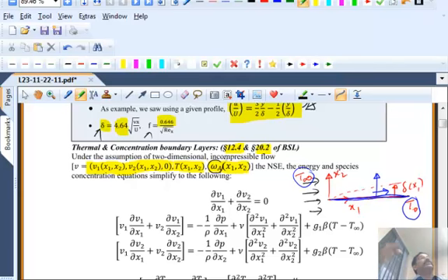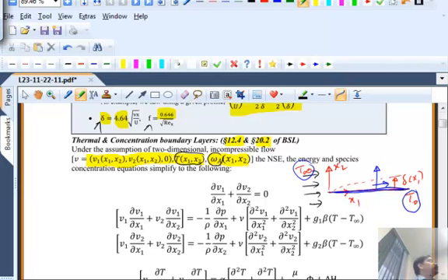So there is a mass transfer that can take place from such a horizontal plate, and that is governed by, again, diffusion and convection of the mass, the species. The species here is A. Similarly, the heat that is being conducted and convected is governed by the energy balance equation. Under the assumptions that there are only two velocity components, V1 and V2, V3 is 0, and they depend only on x1 and x2, you need to simplify the continuity equation, which we have done before, and you simplify the Navier-Stokes equation, the full Navier-Stokes equation.